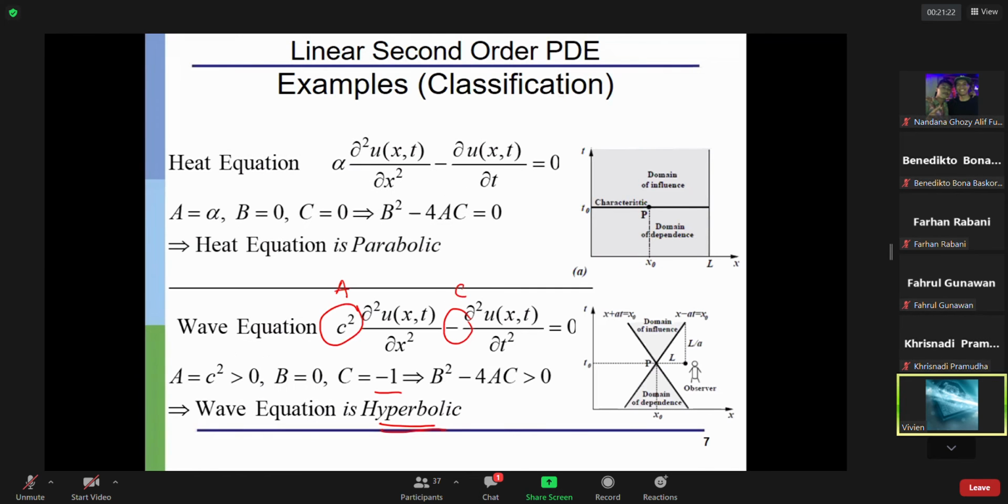Okay, so we will see next the parabolic equations. Here, for example, we have the domain in x and t, where t is time and x is the spatial direction. We can imagine this as a 1D conduction in a rod, for example. We have the ends held at temperature 1 and temperature 2, which act as boundary conditions at the end sides of the rod. And then we want to find the temperature distribution inside the rod. So this will be 1D heat conduction.